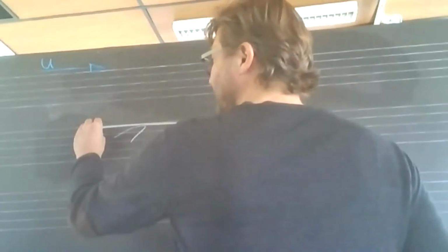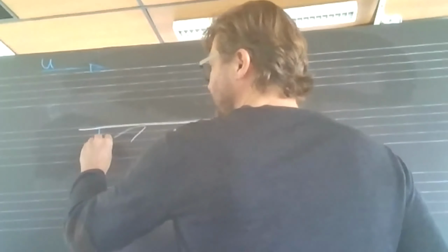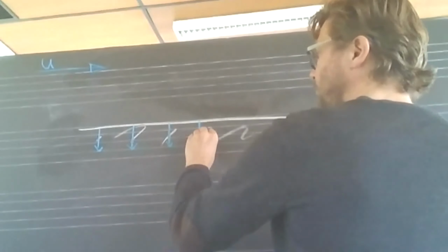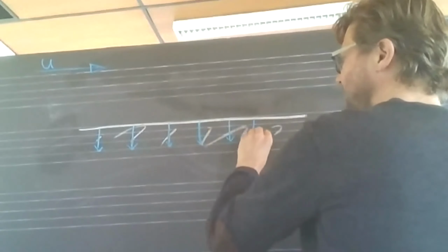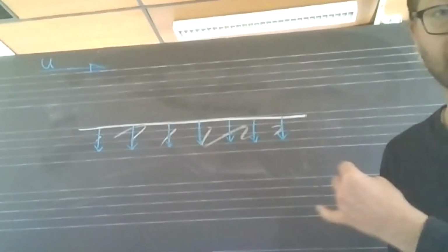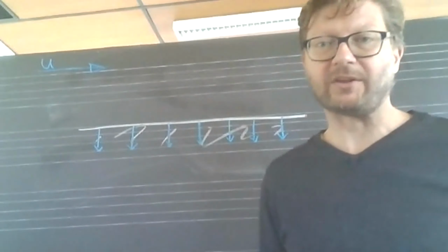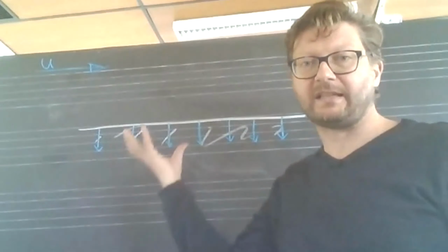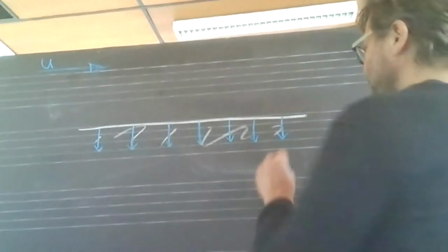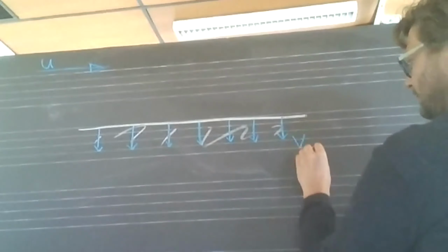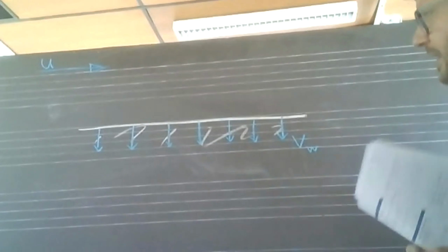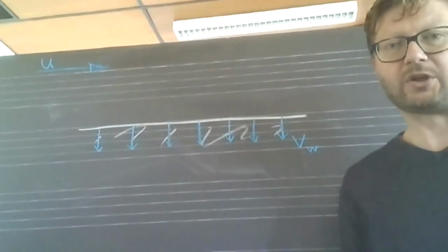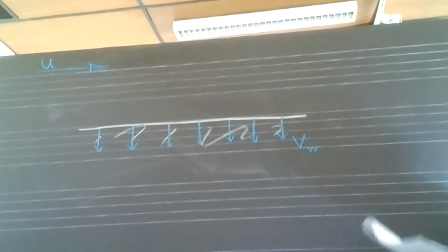Porous in the sense that we can suck a little bit of air through the wall. So in practice, we'll see a picture of a test airplane by Airbus. They actually drill little holes in the surface of the wing, and they suck out some air. And you make sure you put a pump there such that air is sucked out from the boundary layer with a constant velocity VW.